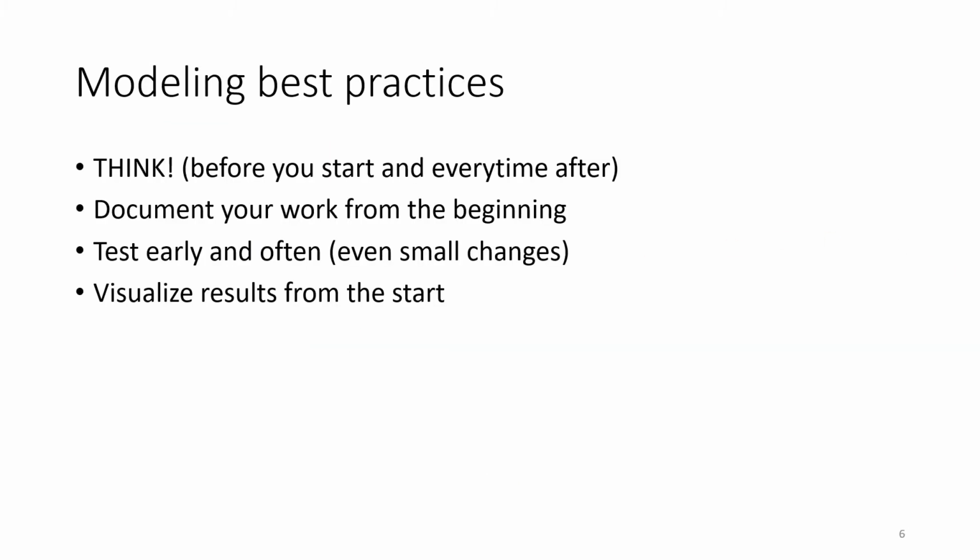So I have very few best practices I want to give you at the head start. The first and most important thing is think, right? The usual way students do is they start the software and they're just clicking around and trying to get things working, without any kind of concept, without any pre-arrangement. So really be careful. I always start a simulation with pen and paper, trying to make a sketch of the geometry, making clear, okay, what kind of boundary conditions do I have?